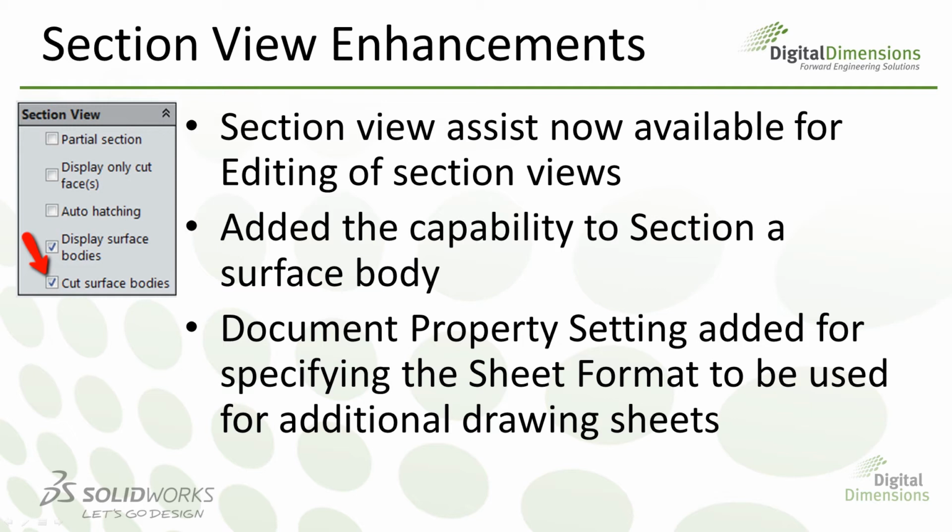Keep in mind that if you edit a section view manually by editing the sketch, then you kind of destroy the ability to utilize this section view assist tool.